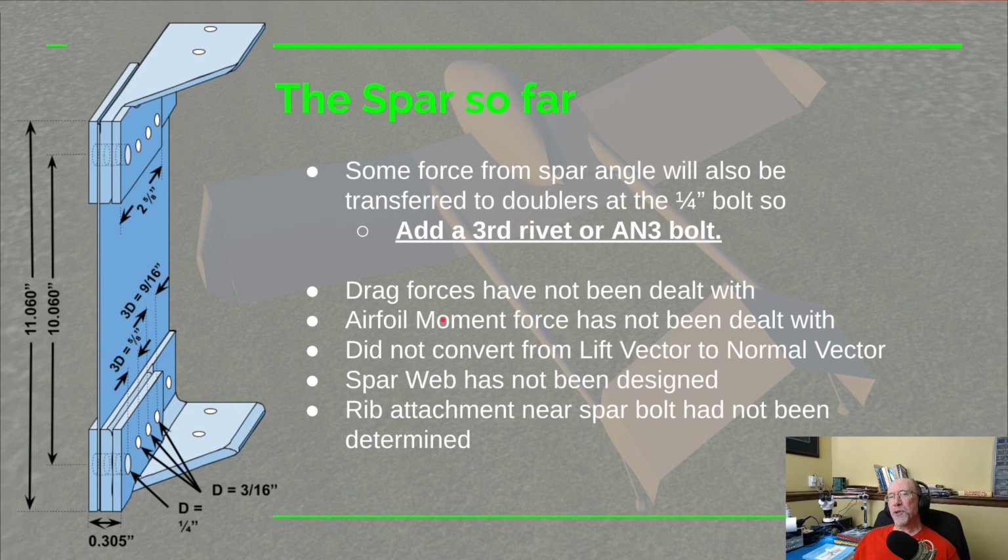The airfoil also has a pitching moment. That's going to change the forces on these bolts also. So it's essentially going to change the shear forces up here. There'll be shear force on the rear spar and a shear force that has to be carried on these bolts up here due to that pitching moment. So that's going to change the forces on these bolts.